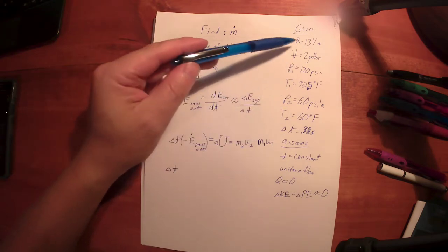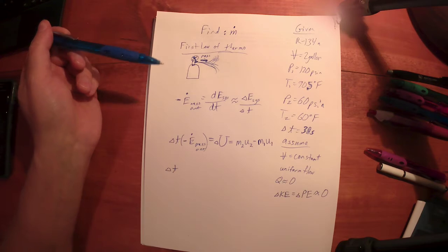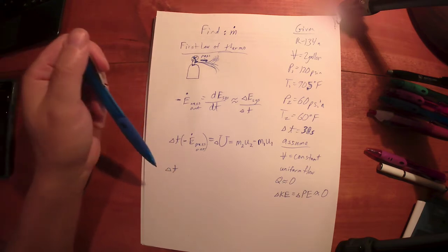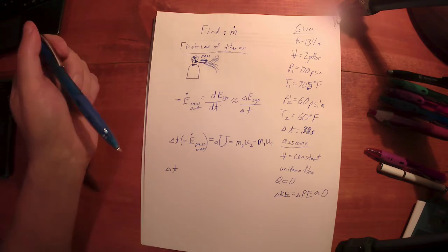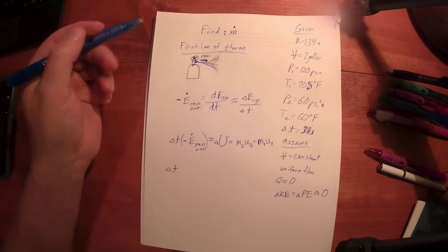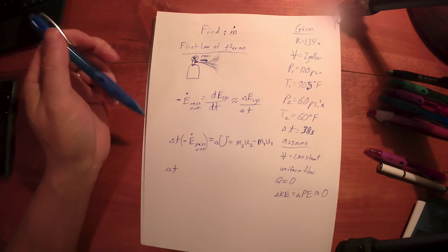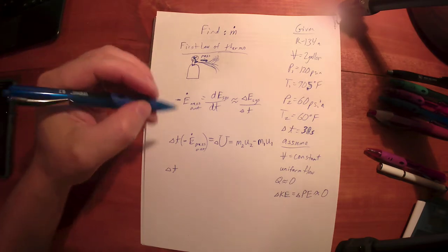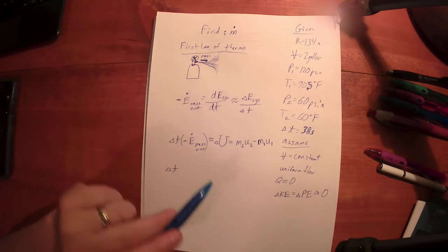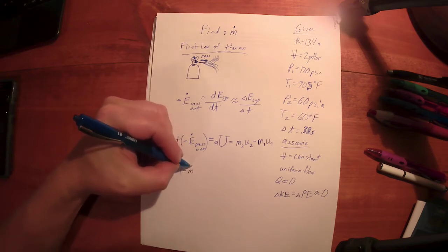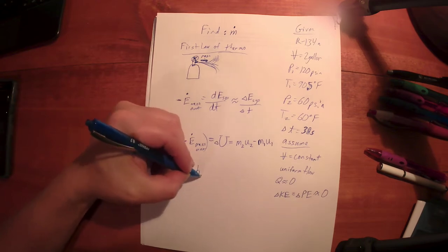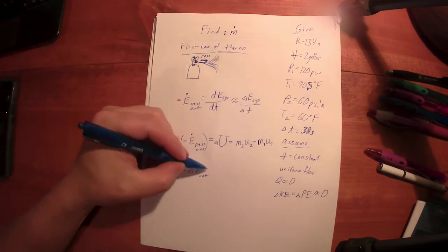If I knew the area of the outlet, which would be really helpful, then I could write this up as a second order polynomial as a function of the speed, and we could solve possibly for the speed. It gets pretty ugly. So it's a little more straightforward in the analysis if we just assume that the kinetic energy of the mass out is negligible. So that just simply means that I've got minus m dot times h out, and this is the m dot I'm looking for.